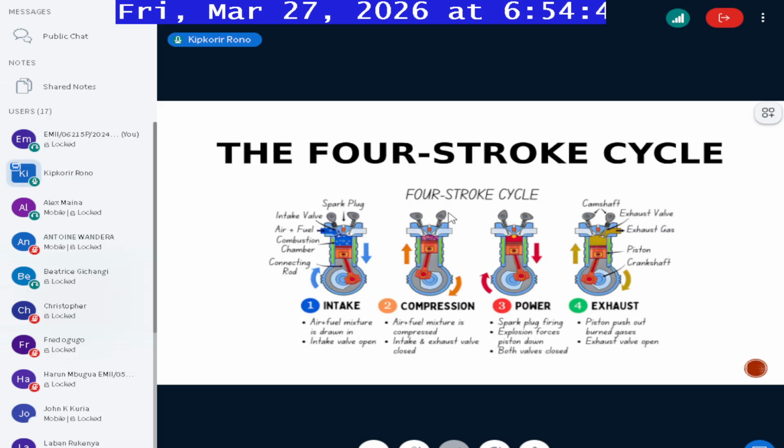One, you have the fuel injection system. A fuel injection system could be something like a carburetor, for instance, that takes fuel from the fuel tank. The work of the classical, conventional type of carburetor is that it first of all has to atomize fuel. Fuel cannot burn while it's in liquid form, so it has to be broken down into very tiny particles, like a tiny mist.